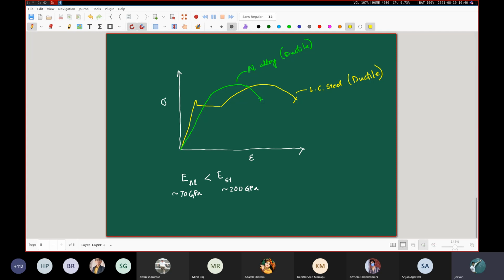So we have been discussing ductile materials. Now, there are a bunch of materials, very structural materials also, day-to-day materials, which are not ductile, as opposed to this, they are brittle. So what is the hallmark of a brittle material? What is the main principal feature of a brittle material? Who can tell me? Sir, it breaks as a flat surface. Okay, breaks as a flat surface. That you will learn certainly in your experiments, but in terms of the deformations, the strain at fracture point will be very less. Right, that is the correct thing.